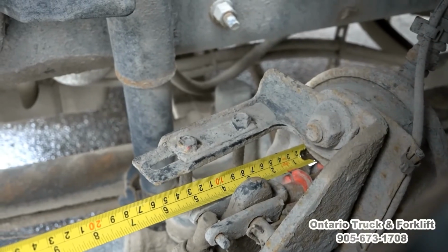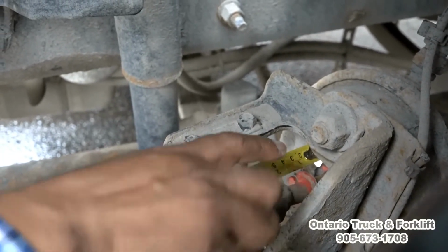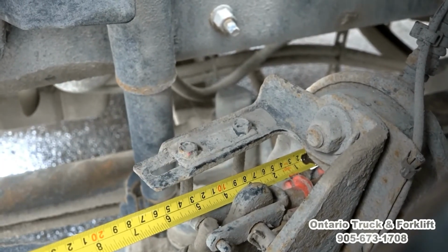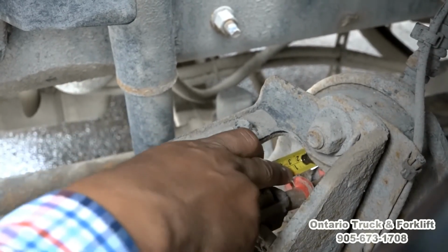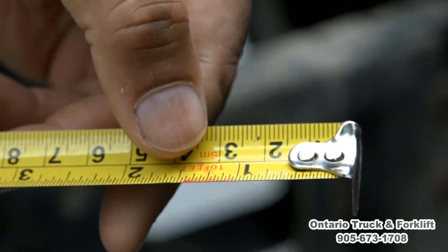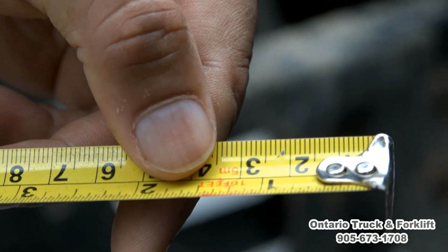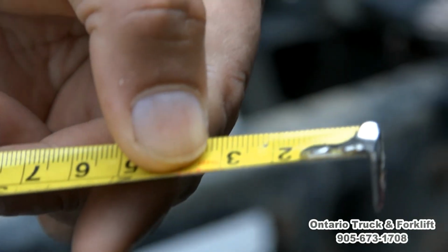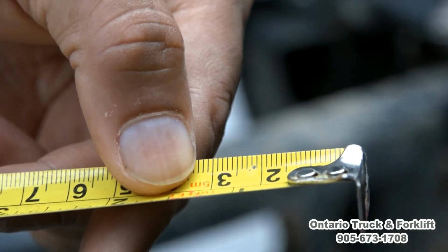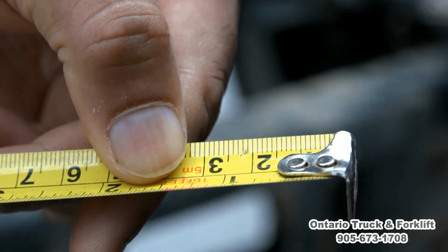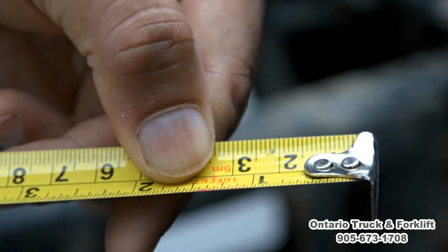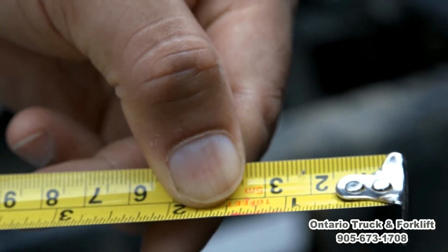Now we will measure the push rod stroke. We measure from the brake chamber to the mark we have there. Let's put our finger there and bring it out. You can see it. We measure the push rod stroke at about 32 millimeters. For this brake chamber we have an adjustment limit of 51, so our brake is within the adjustment limit. If it comes out more than 51, then our brakes are out of adjustment, which is a defect.